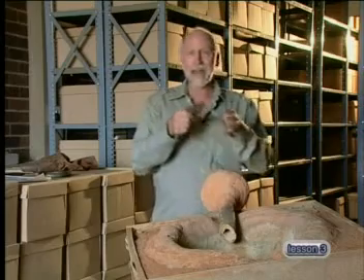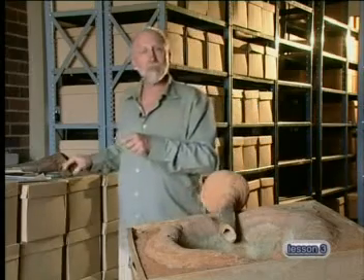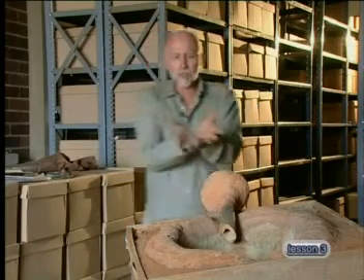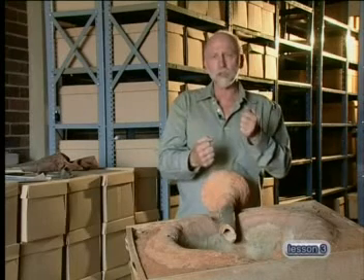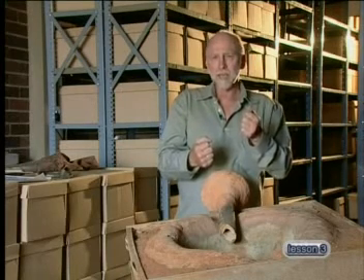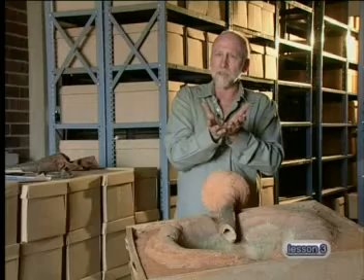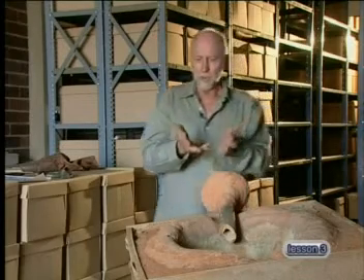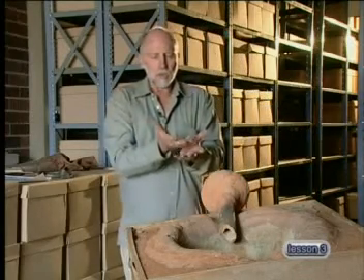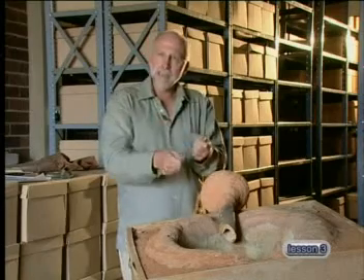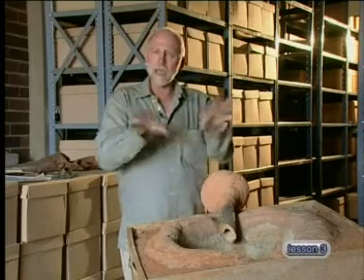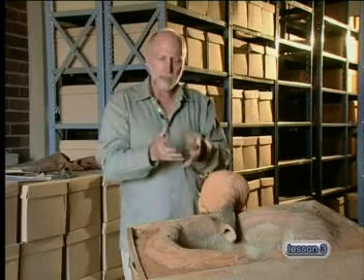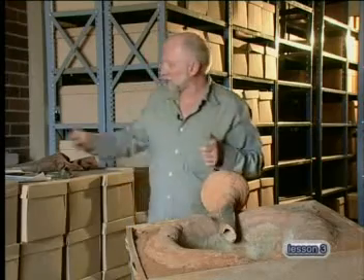They take that iron and go to a smithy area. That's just where you've got a hearth on the outside. You still have bellows because you want to get it fairly hot, but now it's an oxidizing atmosphere and it doesn't have the same chemical, physical effect. What you're doing is getting it hot enough that you can hammer it, and you're breaking away all the bits of slag you don't want, making it into something.